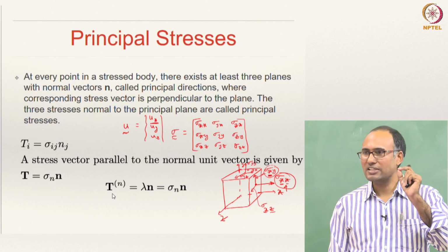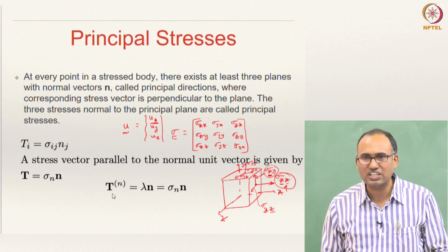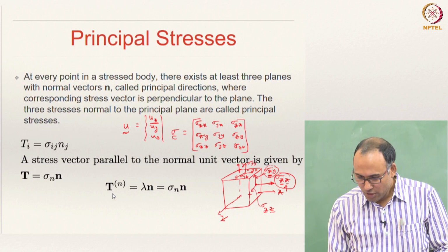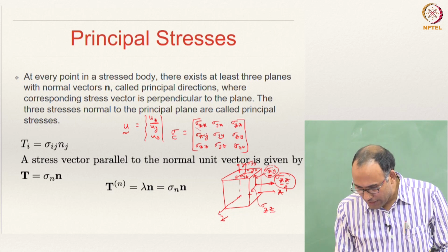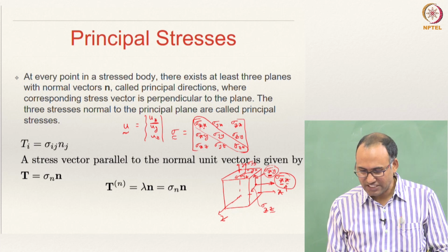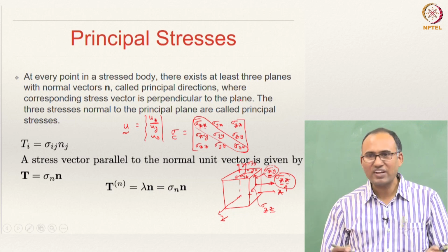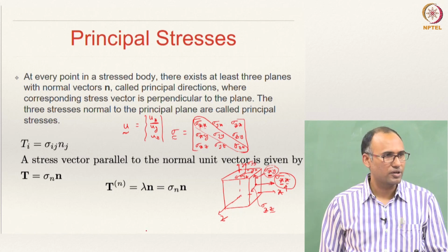So, the order is nothing but the number of indices that are required to represent all the elements of that particular physical quantity. Okay. So, if you carefully observe, all the diagonal elements will have the same index, if both first and second indexes are same. That means it is a normal component. All the off diagonal components are your shear components.